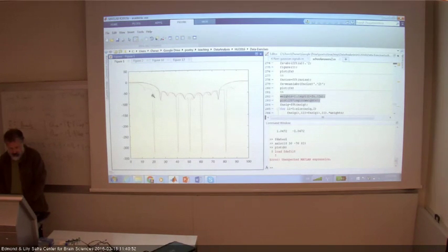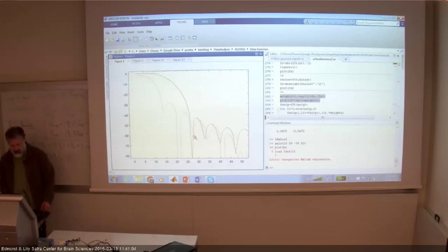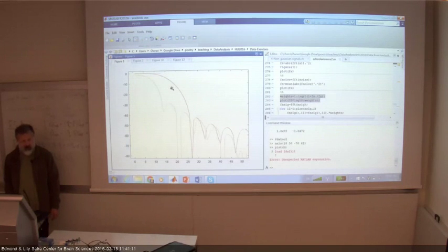This is what I wanted to show you. Yellow are the weights we calculated from the Wiener-Hopf, and red is the transfer function of the filter that I designed. So you see that it's less low passy. It transmits more frequency than I would like it to transmit. I can get the corner frequency even further out, but otherwise it's not dissimilar. And that's the point of using this. We want to use the Wiener-Hopf theory as a guideline for designing our filters. I could make the corner frequency even lower, in order not to transmit this range of frequency here that Wiener-Hopf says I should attenuate, and that my filter does pass to some extent at least.